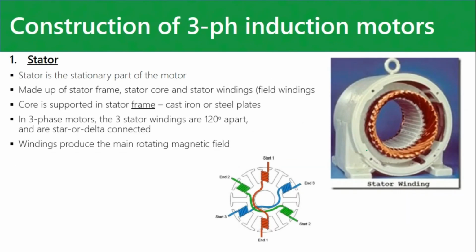So there's our stator winding. You see our 3-phase stator winding looks like this. They wound them separately, and then they slide it into that yoke. So the 3 phases are 120 degrees apart. Each one of those phase coils produces its own magnetic field. If you combine them, it actually comes out to one magnetic field, which is a rotating magnetic field. And it rotates inside, like that, at synchronous speed, ns.